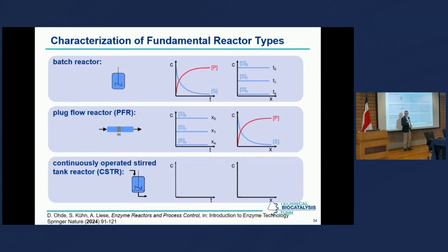And then you have the two kinetic parameters, Vmax and Km. Vmax is the maximum rate. And the Km value is a specific concentration of starting material at which you reach the half maximum rate. So if you get the half maximum rate here, you go to the curve and go down, that's the Km value. Now the crucial question was, how can we correlate this? And the question is, which continuous reactor of those two concepts is more expensive?